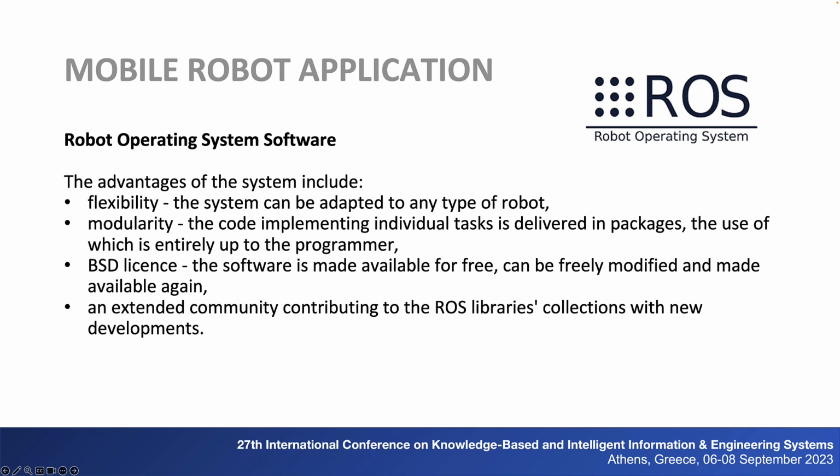Each message is sent within the topic specified by the node. Individual nodes can publish a topic, publishers, or subscribe to it, subscribers, to make use of the messages contained therein. The ROS master, which gives each node a unique address, and informs them of published topics, is responsible for the correct operation of the system.